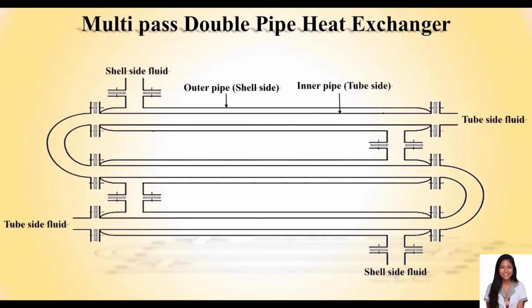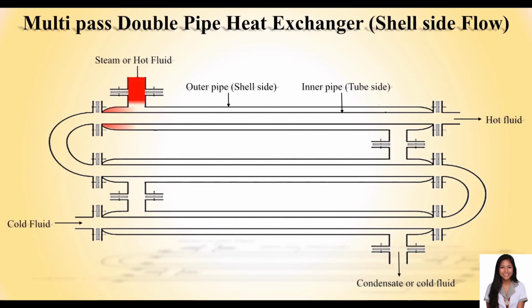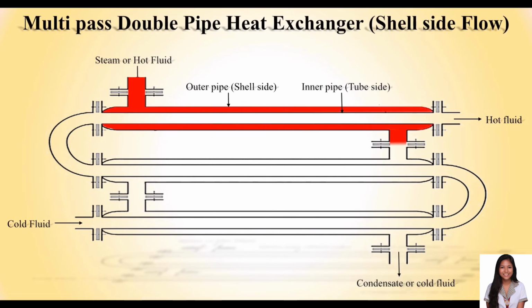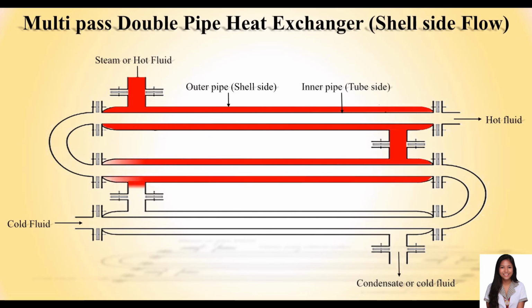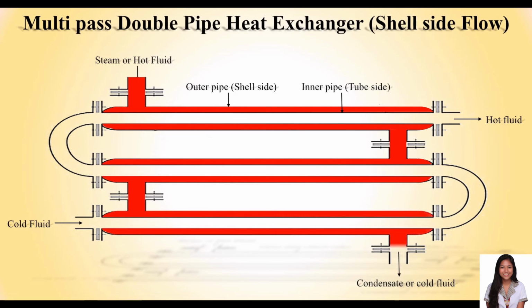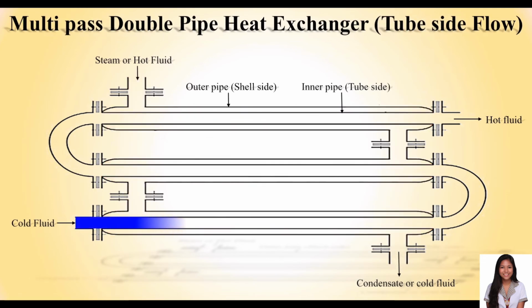Under comparable conditions, more heat is transferred in a counterflow arrangement than a parallel flow heat exchanger, because generally the temperature distribution in the fluids are different. This in turn influences the heat transfer coefficient. Despite the possible identical temperature differences, the heat transfer coefficient is therefore also dependent on the direction of the heat flow. The higher the heat transfer coefficient, the higher the heat transfer due to convection. Heat transfer by convection is directly proportional to the heat transfer area and the temperature difference which exists between the